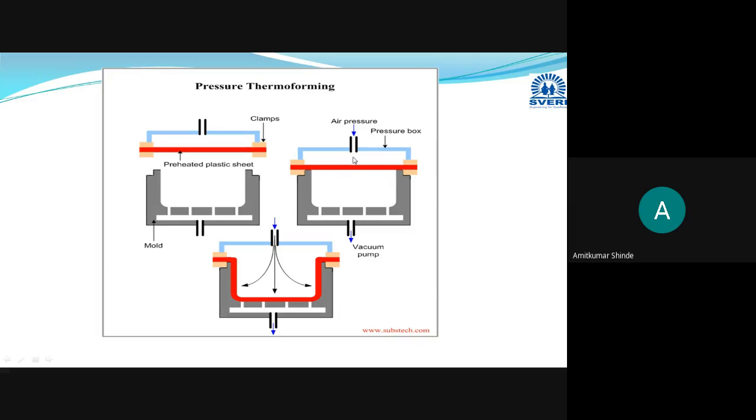Now, due to the air pressure, what will happen? This air will flow and apply force. Due to the heating process, this thermoplastic material has become soft in nature, and due to that force, whichever material or sheet is there gets pressed against the mold wall.